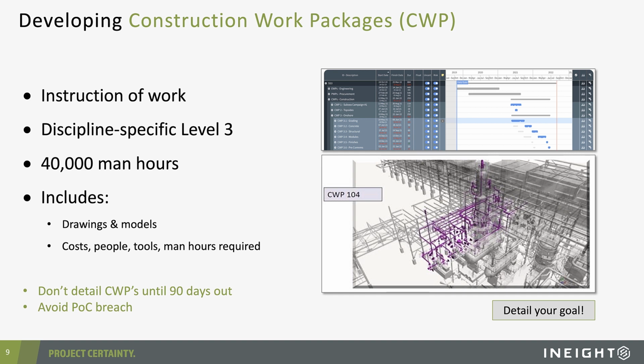And I think what is so brilliant about AWP is if we can define these elements that are required for on-time execution, as we are doing here as we detail out our goal, that list actually becomes this constraint register. In other words, let's not actually start execution if indeed some of those constraints are present. So this concept of not just defining the construction work, but actually listing the associated elements that enable the execution of that work, flip that on its head, call that a constraint register and manage that constraint register. Again, that's such a different way of planning relative to traditional CPM planning and scheduling.